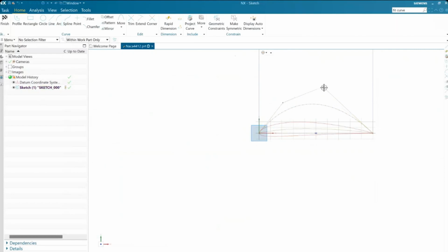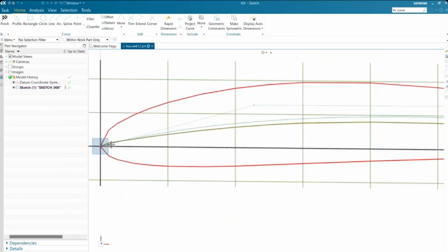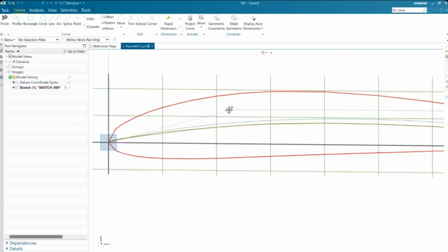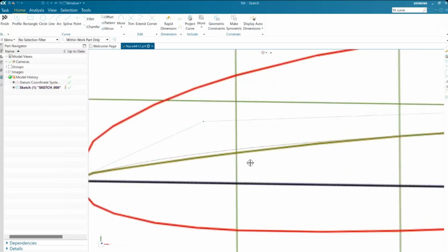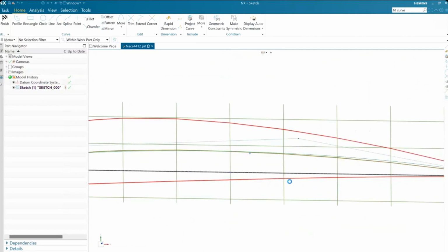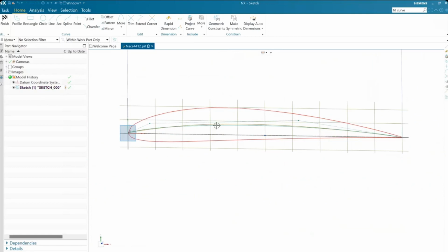So I'm making a construction, and I'll take these 2 poles, and essentially I'm going to make them so that this line matches the camber line. Now the important part is you match the leading edge and the trailing edge as much as the middle, because it's very important for constraints and dimensioning reasons. Now this is perfectly fine.